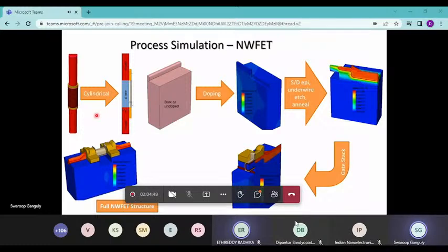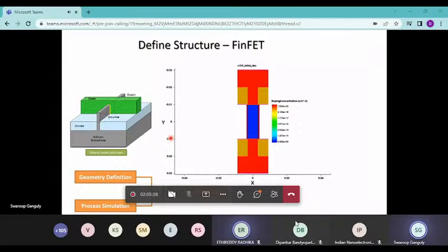What I have on the top left-hand side here is a slightly different aspect. Once I've realized the device structure, and ideally maybe it looks like this as a nanowire with a gate, what we actually simulate, in order to make it computationally efficient, might be one part of this. Here, what I'm showing you is that we are simulating this in cylindrical coordinates. We can essentially simulate this very three-dimensional structure using just two-dimensional maths by using cylindrical coordinates. So all these tricks come into play. But let us now get out of this little digression and come back to the main path of simulating the FinFET.